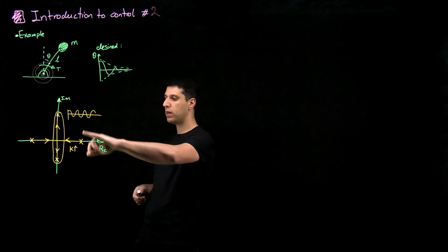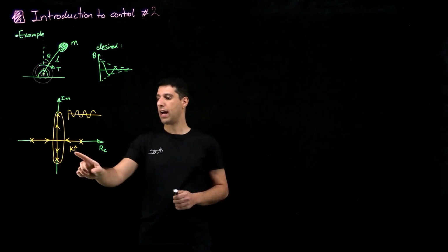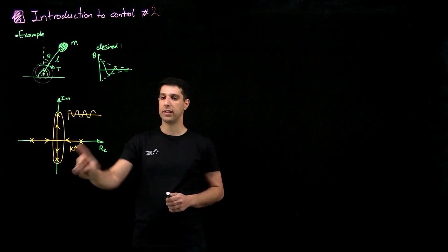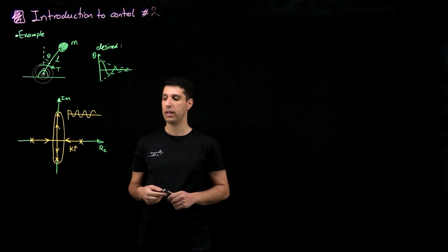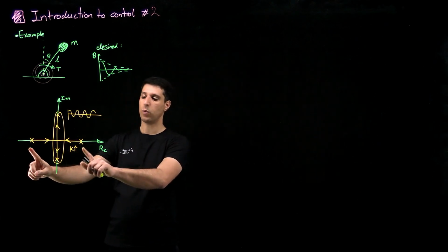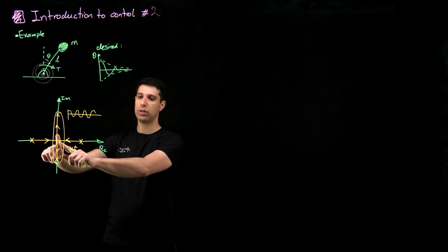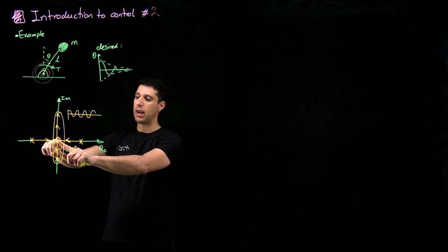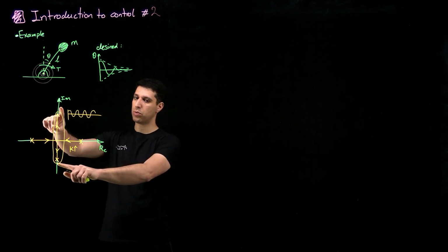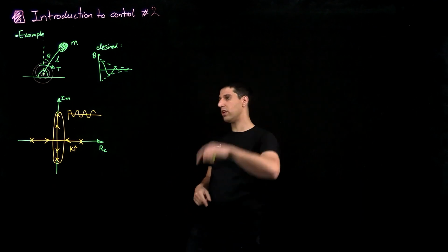And if you remember, this is the root locus of the system. As my virtual stiffness, K, or the control gain, increases, the poles of the system, one of them being unstable, get closer and closer to the origin. And after that, they will start to separate from each other on the imaginary axis.